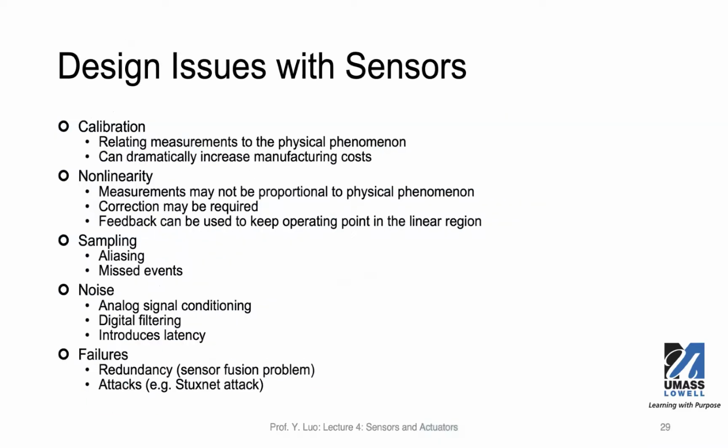If you're interested, there are a lot of details you can look up on the internet about this incident. But the story is, you have to design your system to accommodate sensor failures. That's not just the sensor itself or redundancy of sensors. You have to be mindful about how your control software handles such unreliable sensors.